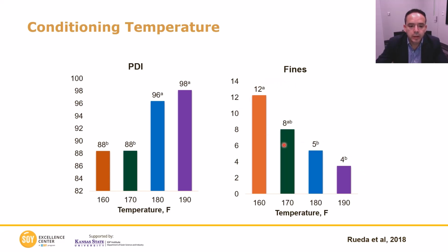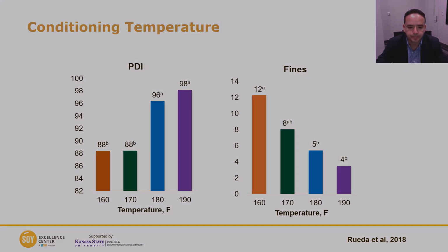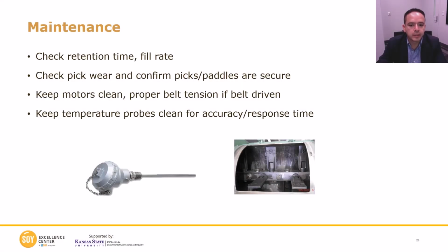We did it this way because if you are just collecting a sample to evaluate the level of fines, then you might not be able to collect a representative sample. But when you collect the whole bag, then you have a better representation. But in general, higher conditioning temperature, better pellet quality, and a lower level of fines. And these are some of the maintenance items that you need to pay attention to during conditioning.